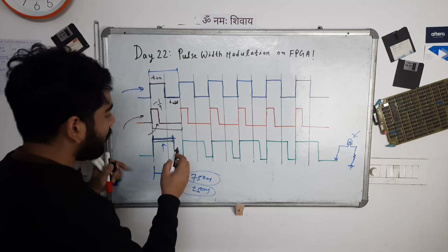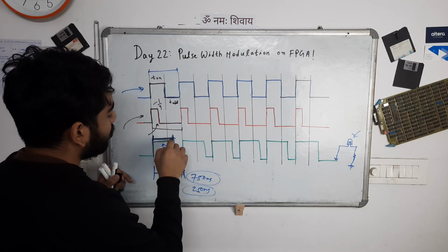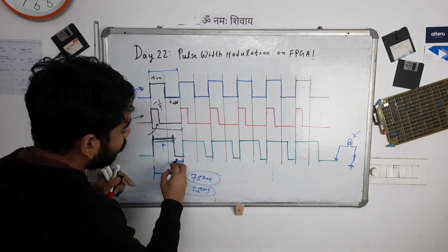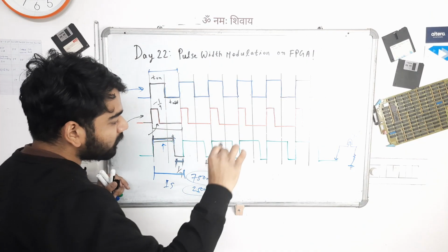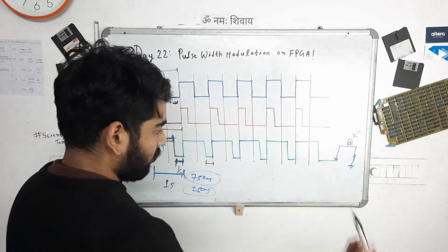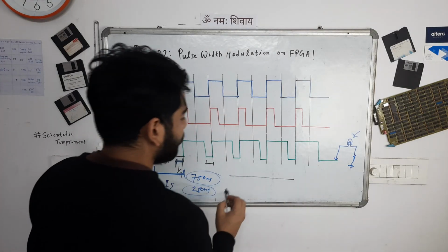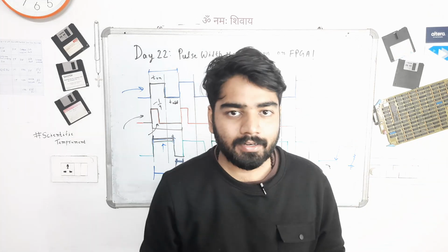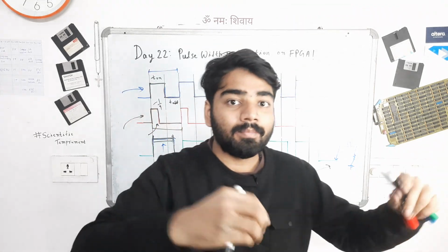What I mean by that is, you do not see the flickering effect, okay? But still the LED is off for quite a long time, right? The brightness of the LED is because it is on, okay? If you have a constant DC signal going into that LED, you will have it on for 100% of the time, right? And that will be the 100% brightness, okay?